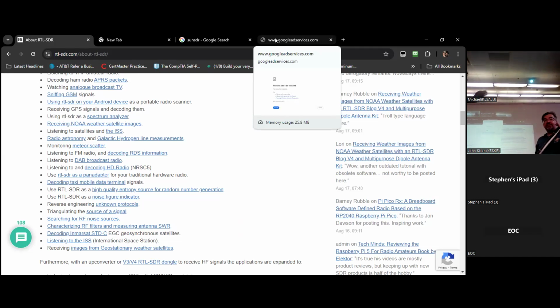To be honest, with my ADSB stuff, I've just been buying commercial antennas. They're only $30-40, depending on what you're wanting to do. This one's for 978, which is UAT, the lower end tracking for commercial vehicles or planes. I find more things on UAT are going to be the helicopters and short distance type things versus something running a full ADSB transponder like a commercial flight or even a personal plane.